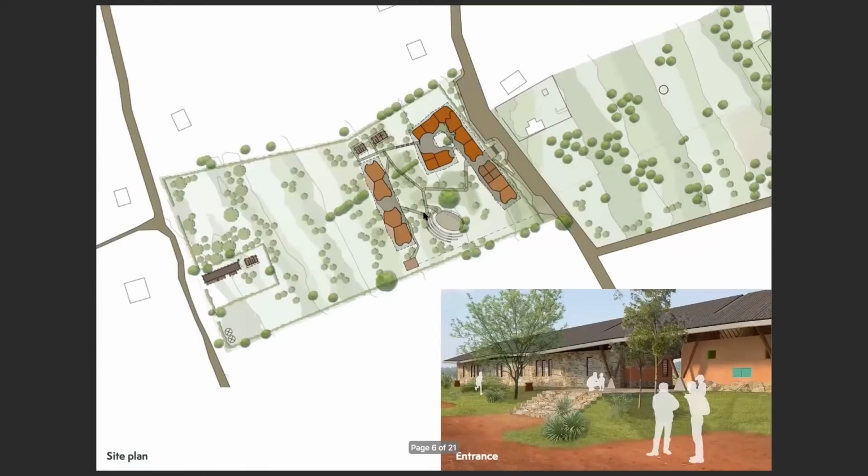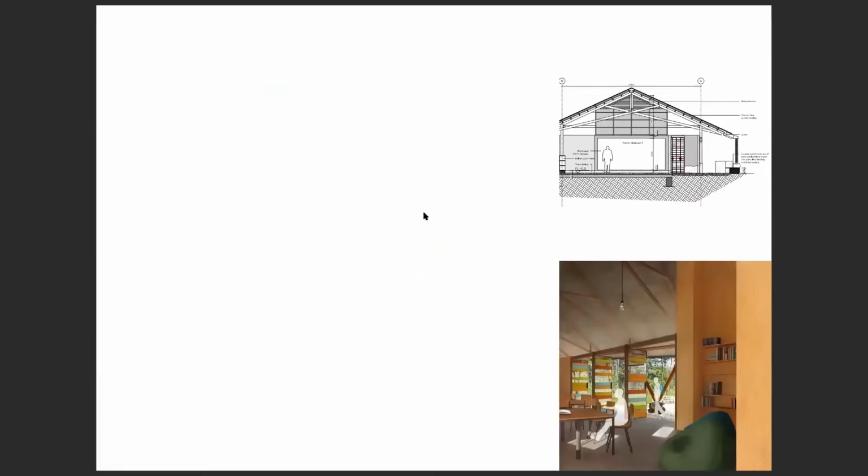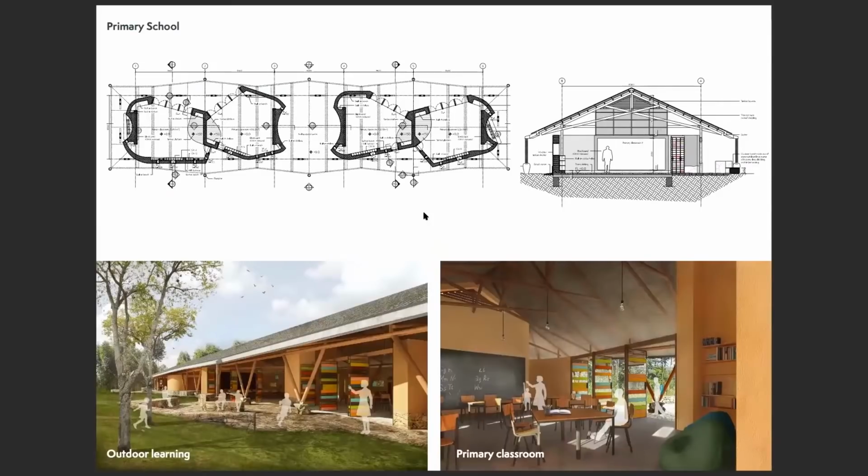So right now we basically have two things: the roof and its frame structure, separate from the wall structure. Not entirely separate, because we're using the gables or the partition walls to brace the walls, but generally the walls are freestanding, which makes them very difficult to design structurally, because you need good strength and good mass to hold them against the wind. The same applies to the roof. You also need very good strength to hold it against the wind, because it doesn't really benefit from the walls so much. Where's the ring beam?